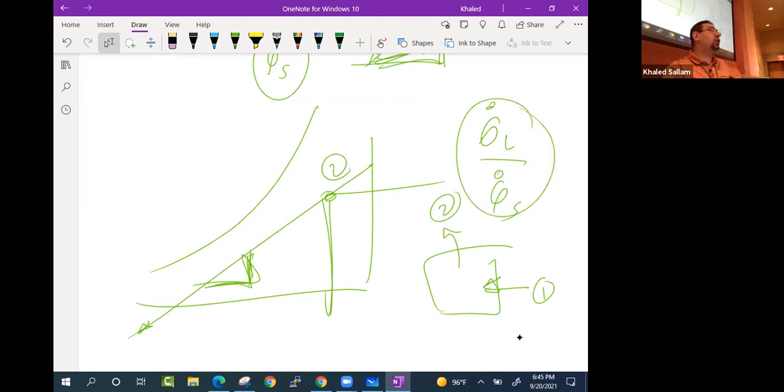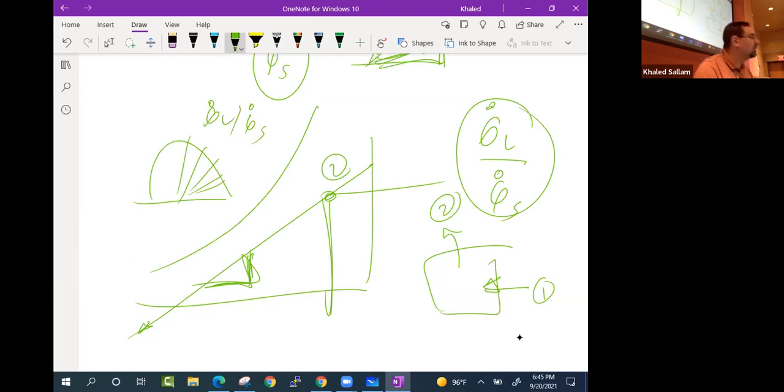Actually, some psychrometric charts will have, on the side over here, a protractor so that you can get the Q dot L over Q dot S. So you find your exit, you draw the line parallel to this, and you will be able to say, I should be somewhere here. Anything along this line, sending it to that space will work for us. Okay?